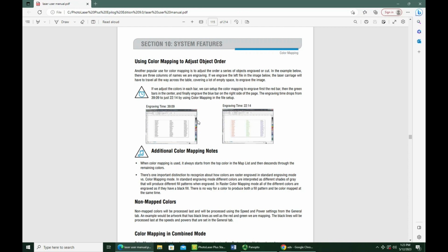But instead they had it set up with one giant file, and the laser would fire over here, travel 2 or 3 feet, and fire over here and step down. And it was going back and forth, and it took over an hour to engrave. And then again, it'd fire over here, it'd hit part of the circle and fire, and then travel all the way here and fire again. So there's lots of dead travel time. If you can break it up, you can do it by colors, and it should decrease your travel time or decrease your total cut time.